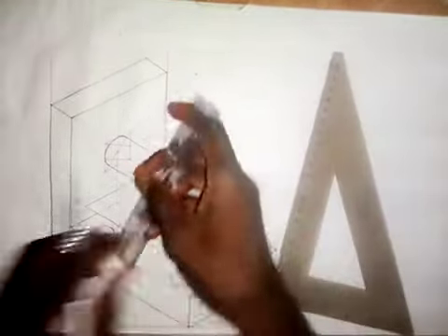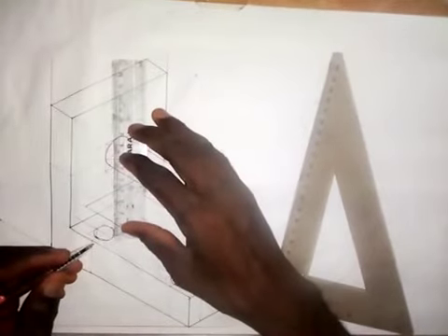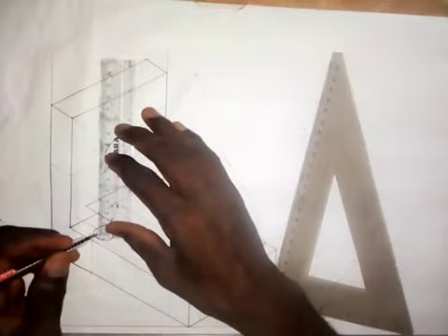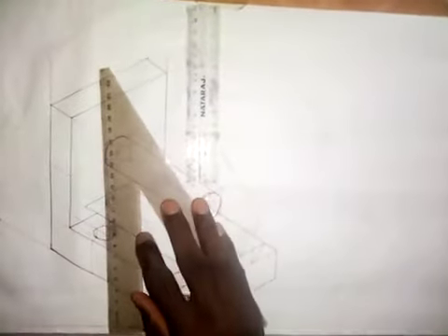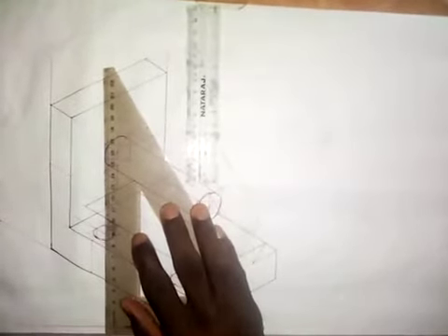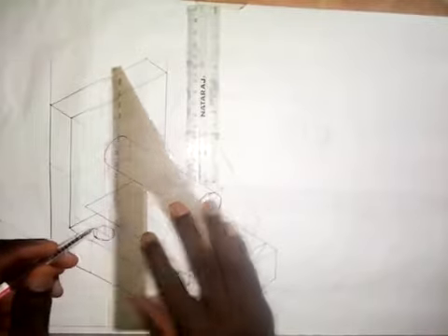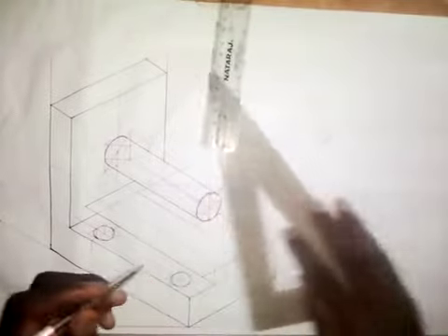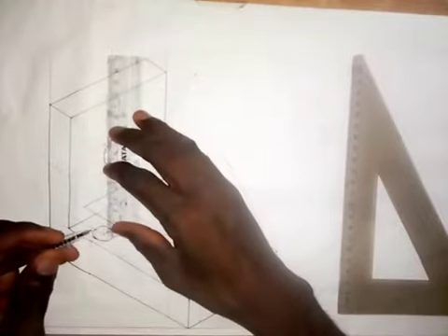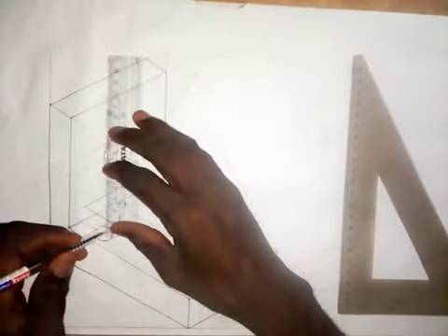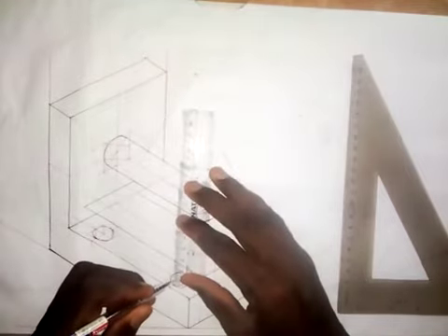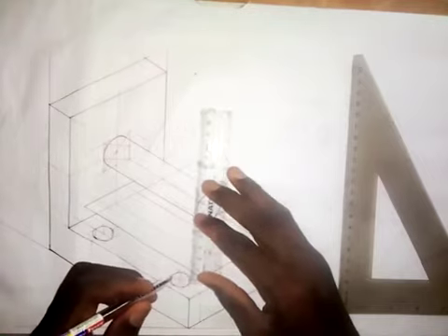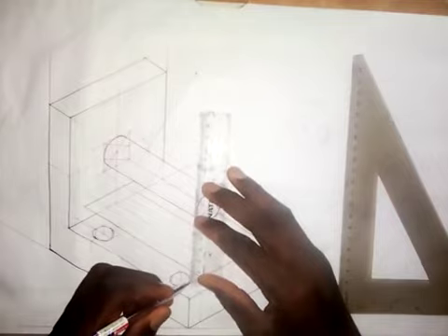All right, so I will now take a measurement of 5 millimeters. So 5 millimeters here. I will take 5 millimeters here also. So I will come to this midpoint here. This midpoint, I will need to draw a vertical line in this midpoint. Very important. I will also do the same thing. So this midpoint, I will draw a vertical line here. So I will take 5 millimeters also on this midpoint line, 5 millimeters here. And I will come here also, take a measurement of 5 millimeters down on this mid vertical line, and then here also I will take 5 millimeters down here.